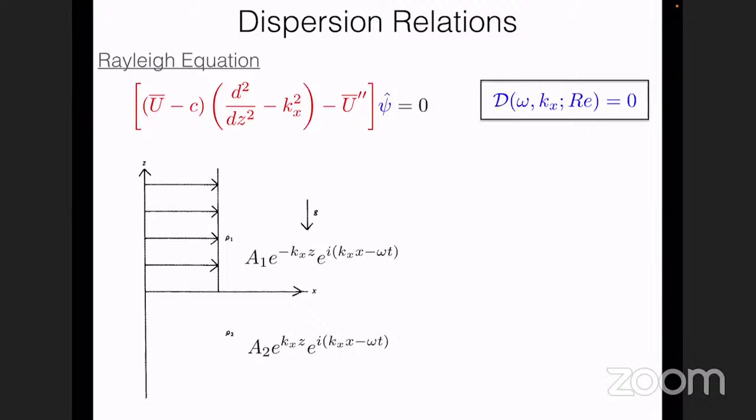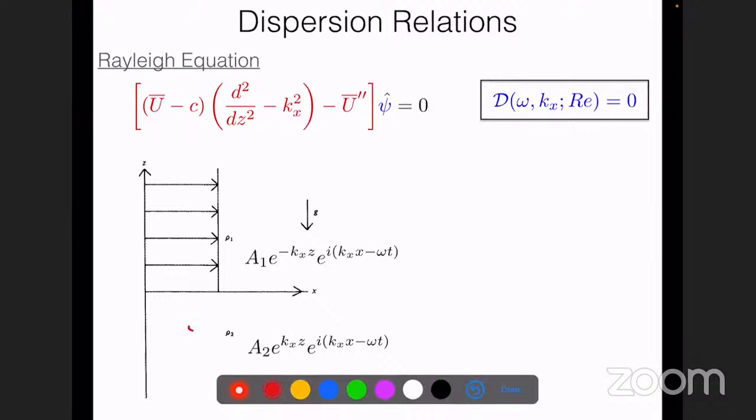So as I said, fluid elements inherently will have a cohesive force between them. If I have a fluid element somewhere here in the center, this fluid element is being attracted from all directions by like fluid molecules. But a fluid molecule sitting at the interface is attracted by its neighbors from the bottom, and it experiences a differential force from the neighbors from the top fluid. And this leads to surface tension.